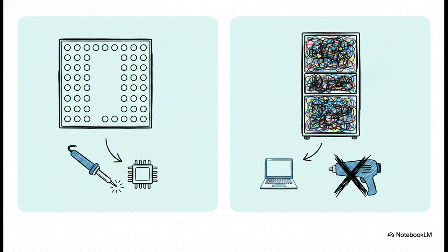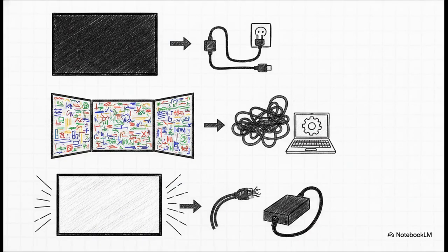But an entire cabinet showing garbled, scrambled nonsense, that's systemic. That means you've got the wrong firmware or a corrupted configuration file loaded onto the receiving card. You fix that with your laptop, not a hot air gun. When the whole display fails, you really have to think system-wide.